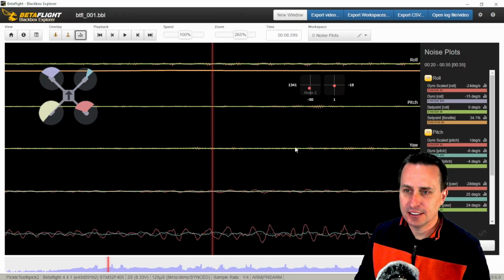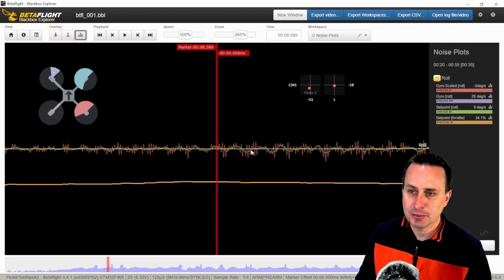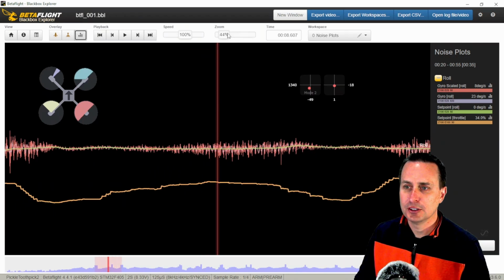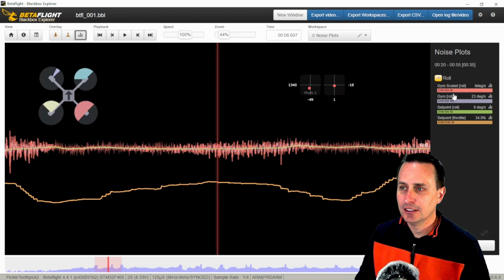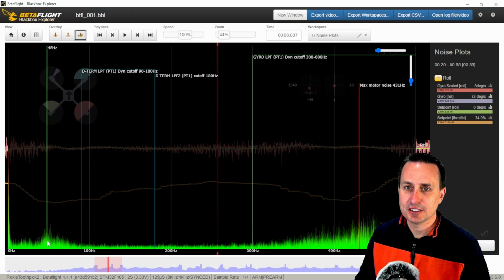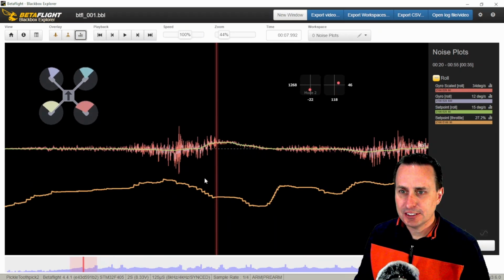Yeah, and you can see those vibrations. It's not like the little motor spiky vibrations. It's something a little less. If I measure point to point here, it's something around the 50 hertz range, which is all those different spikes. I measured 50 hertz there, but it's in this whole region. Some I'd measure point to point would be down in the 40s, some up in the 60s. I just happened to measure one around the 50 range. So there's definitely an issue there.